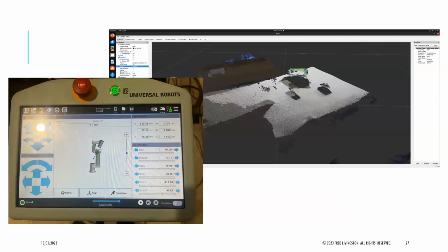So the robot gripper is at this XY position, roll, pitch, and yaw. And that roll, pitch, and yaw, just remember, is the rotation. Roll, pitch, and yaw is actually the rotation in Z times the rotation on Y times the rotation in X. And that will be a 3x3 component. And then you have your X, Y, and Z scale factor. And that will give you a 4x4 matrix there.